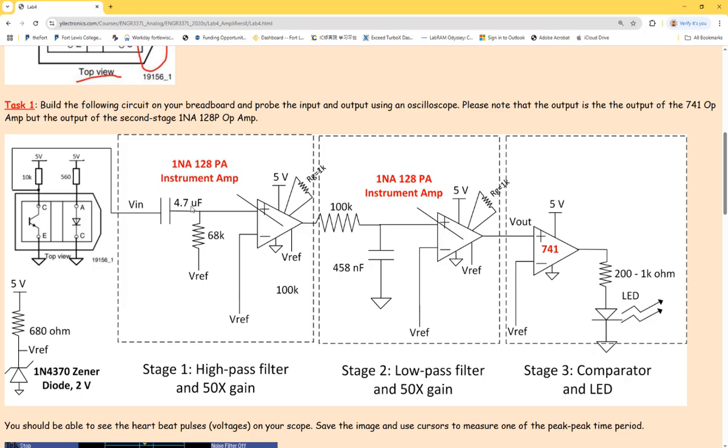So a lot of times, if you don't have any signal being injected into your system, into your oscilloscope, and your probe is not grounded, in that case, you can see a sine wave appear in your oscilloscope, and that is the noise from the plug. It's a 60 hertz from the 110 AC voltage. That's the noise. So a lot of times, for the very tiny signals, we need to get rid of that 60 hertz noise as well. So in one of the filters here, you have to design the 60 hertz removal filter, right, to make it cleaner.